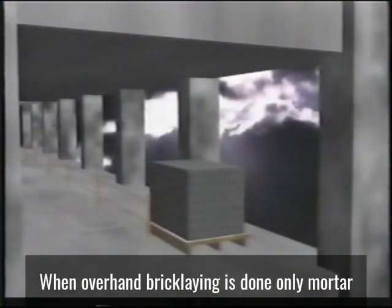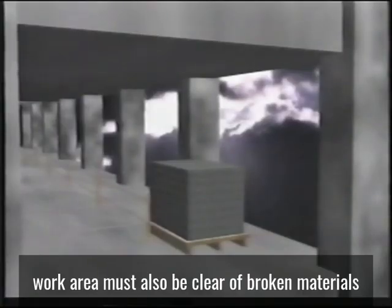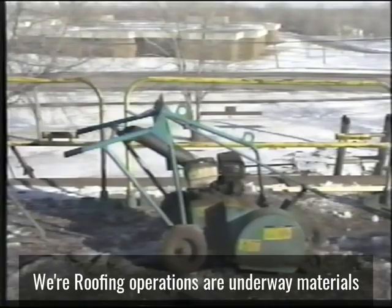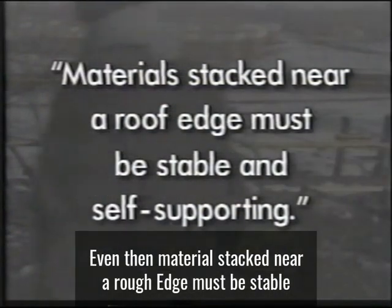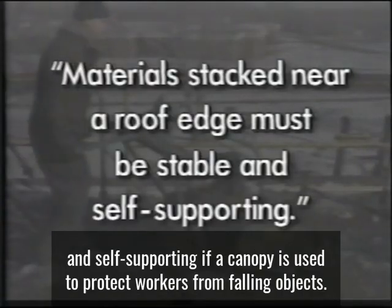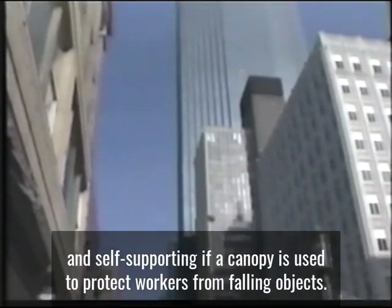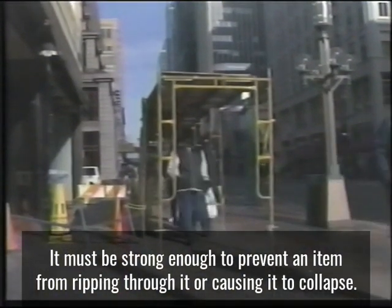When overhand bricklaying is done, only mortar and masonry materials can be stored within 4 feet of the edge. The work area must also be clear of broken materials and debris. Where roofing operations are underway, materials and equipment cannot be stored within 6 feet of the edge unless a guardrail system is in place. Even then, materials stacked near a roof edge must be stable and self-supporting. If a canopy is used to protect workers from falling objects, it must be strong enough to prevent an item from ripping through it or causing it to collapse.